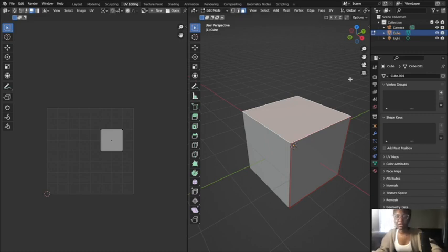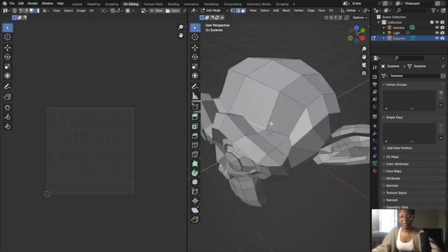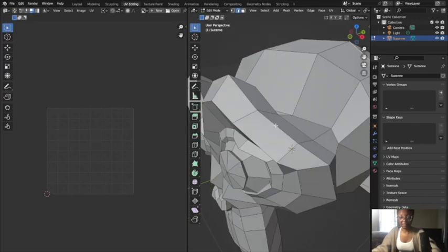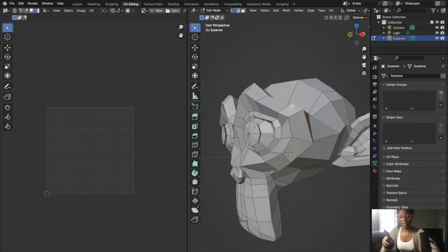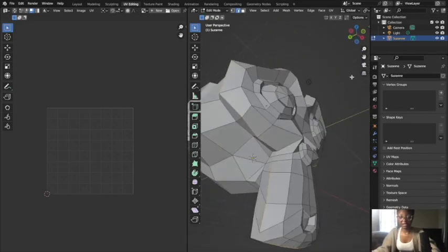It just allows you to separate the mesh, separate the texture or this part of the mesh, so that it can have its own texture set. I would also like to demonstrate this process with the monkey head. So what I'm going to do is select an edge on this monkey, and it's going to create a seam on the mesh. All right, so to select the edge loop, I'm pressing Option on my keyboard and clicking the mouse, and this is going to allow me to select the edge loop.